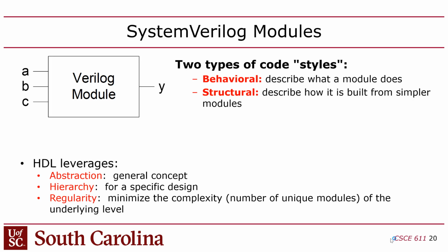You might say, well, wait a second, what are the rules, though, for behavioral code? Well, basically, Boolean logic is behavioral. So you could put Boolean logic, things like state machines, multiplexers, simple multiplexing behaviors that we use a ternary statement for. I'll talk about that in a minute. What else? Basically, anything that can be resolved to a truth table in the end.